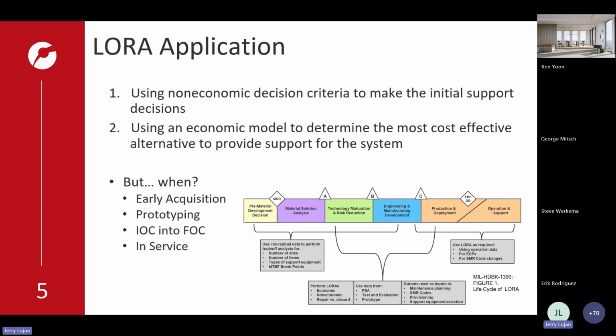When we're talking about early days, right? So pre-milestone A up through, say, a little bit after milestone B, we're going to be looking at things like those larger items, facilities, number of technicians, what are those limits of MTBF that we can support within a repair facility. Like we could have a depot line that could handle X amount of engines at a time, per day or per month. Does the early look into the system look like we're going to break that or not?